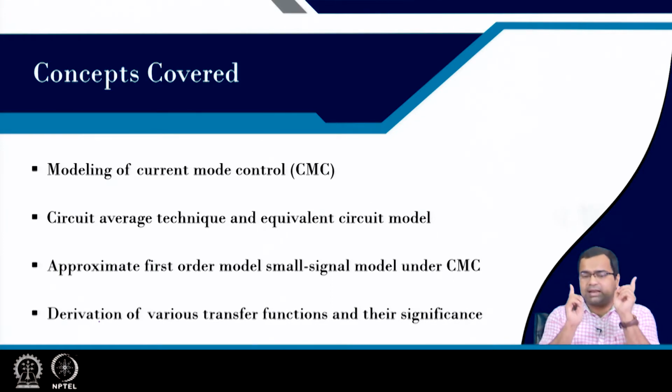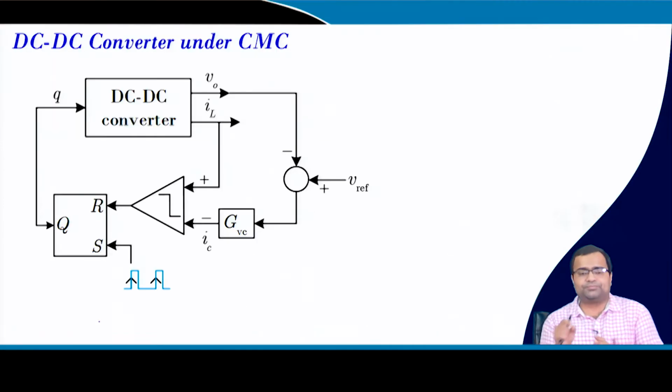Another aspect we will see in current mode control is load regulation, which we will also keep in mind, because in the earlier lecture we saw current mode control offers excellent line transient response. So, there is no problem with line regulation, but we want to investigate what the aspect of load regulation is in current mode control.